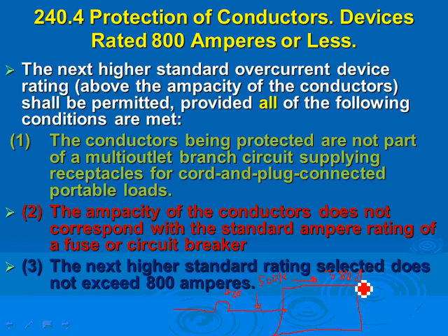Now, make this an 800 amp. This is an 800 amp, typical. Then this will be 2 sets, right? 2 sets in every phase. And this will be multiplied by 2 now because I have 2 sets. And that will get you 760 amps. Is this legit? Yup. Why? Because the next standard overcurrent protection device is what?